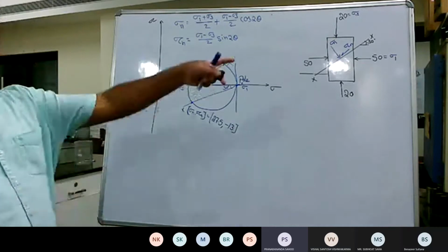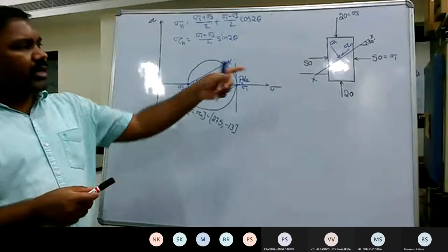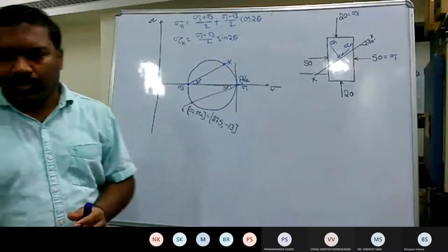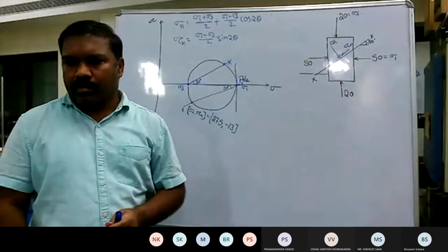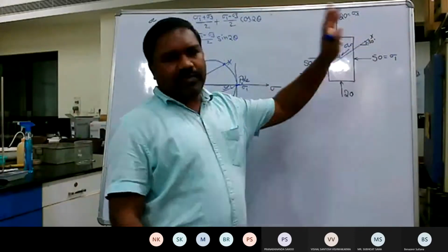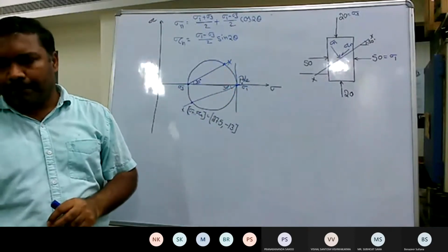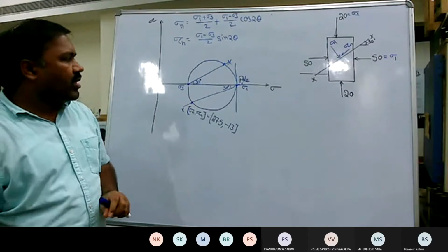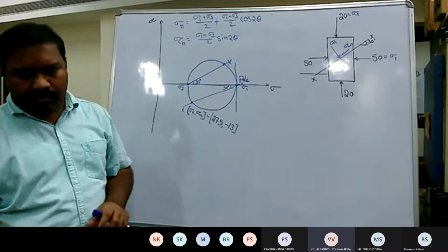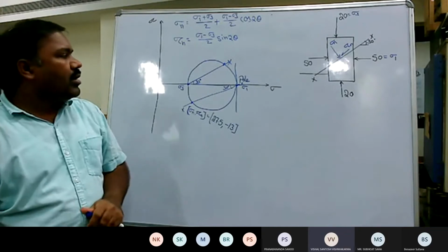Yeah. But here in that case theta 30 is okay. But in this case, how do you determine theta? Suppose this is the major and this 30 is perfectly alright, then we will get the failure plane here. Sir, here 30 degree is made with the horizontal, which is the minor principal stress plane.